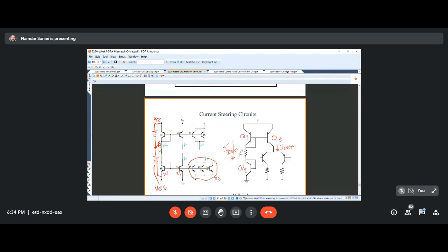Meanwhile, we talked about how we can turn around the direction of the current in order to provide a bias current for PNP transistors, when we have differential pair amplifiers made by PNP. And also we learned about scaling factor, how we can scale the reference current to a number of reference currents.